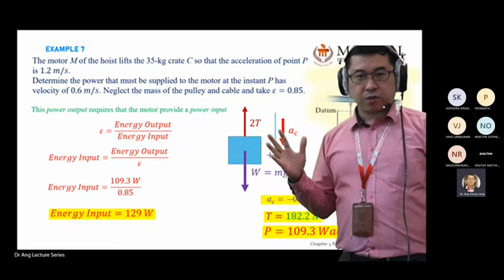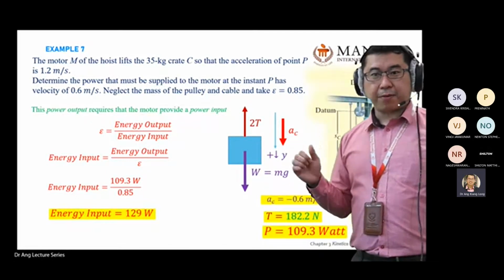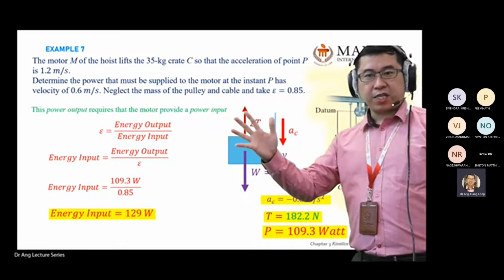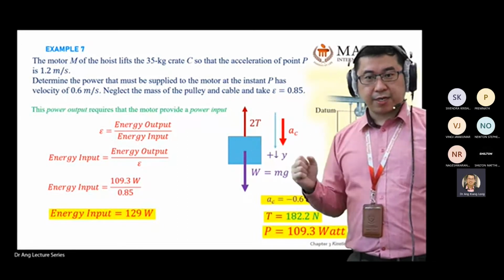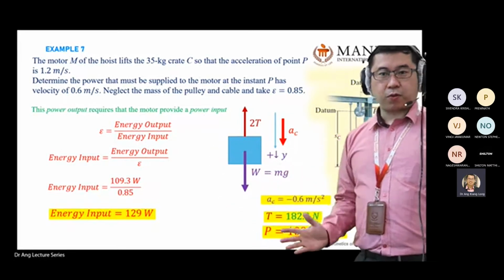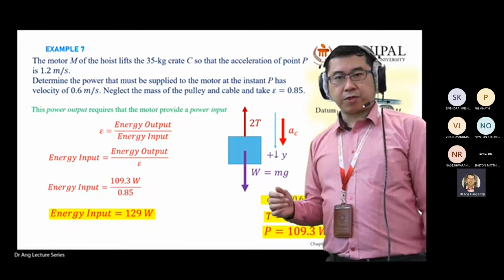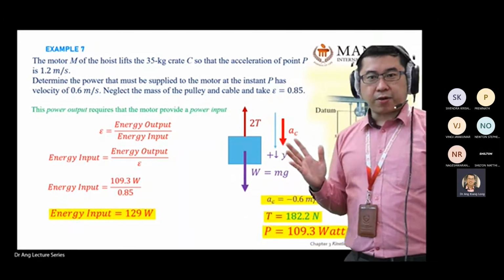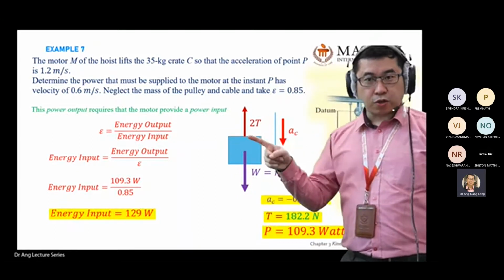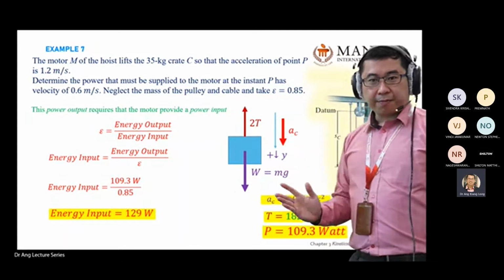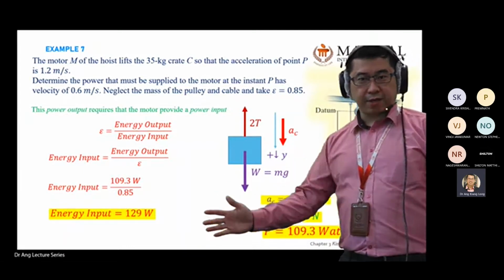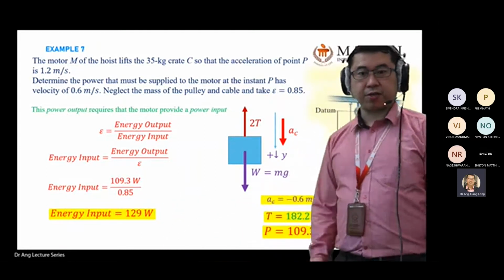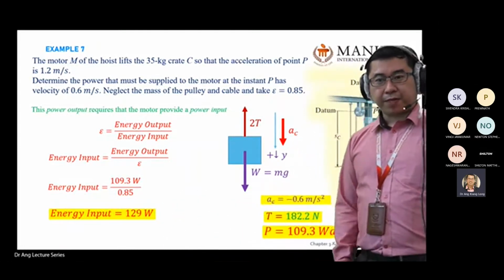There will be very high points for your free body diagram, because once your free body diagram is correct, the rest just follows the standard procedure or standard strategy to solve. My concern is that if you're not good at free body diagrams, then something will be missing in your equation, and you will have a lot of errors in your calculation.